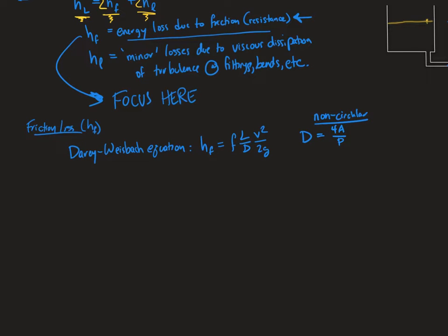Generally speaking, let's imagine your conduit were rectangular but not all the way full. Then the area would be like this, and the wetted perimeter would be this portion on the outside that is wetted. We won't be using that in here. We're just going to use it as the diameter of the pipe, because we're just going to use circular conduits. In your coming courses you might come across this, but that's just something to be aware of. For us, for circular, this is just going to be the diameter of the pipe.